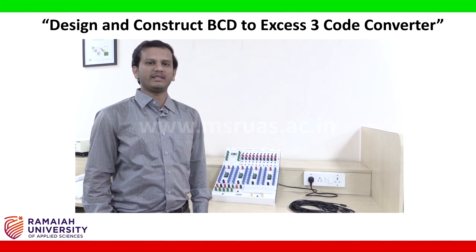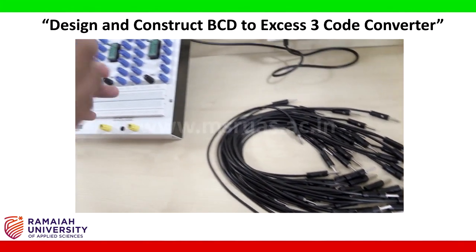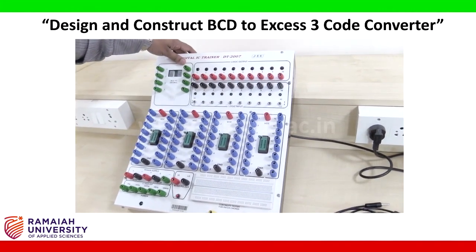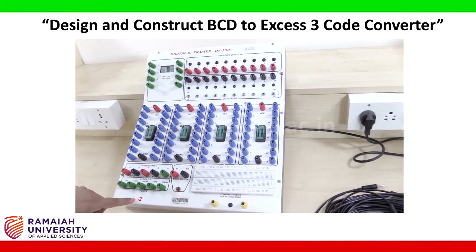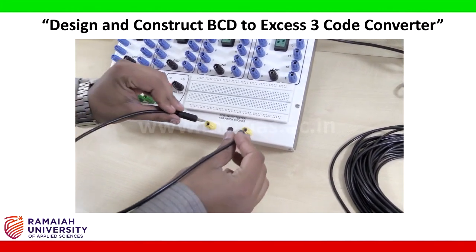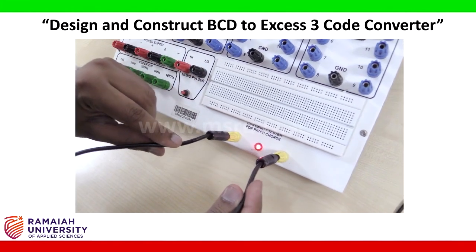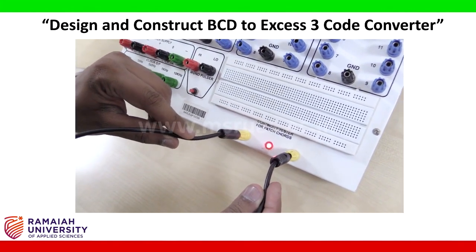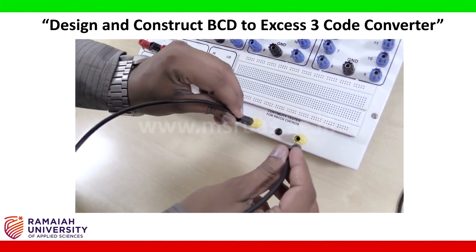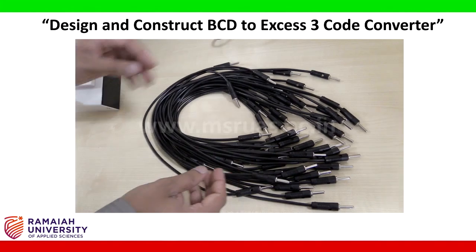Before using any patch cord to connect the given logic diagram, we have to check the continuity test for each patch cord. Take the patch cord, turn on the power supply to the digital IC trainer kit. It is turned on now. Now place the patch cord between the continuity tester knobs, and you can see there is a LED on and there is a beep noise. So this means the patch cord is working fine, and similarly we have to check the continuity test for all the patch cords which we are using for the experiment.